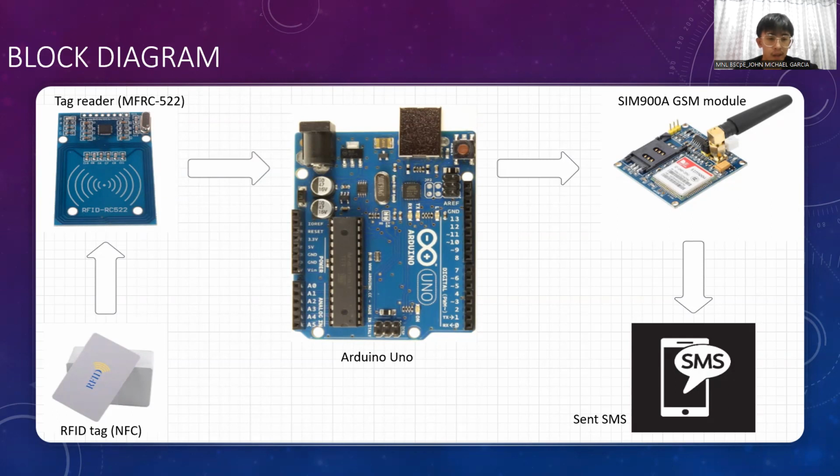And since we have arrays as an example of a database, if the student number is 20, then the 20th data will be called, where it will be the name of the student, its course or section. The number of its guardian will be pasted to the designation number of the SMS receiver. So after the SMS was created using arrays, then the Arduino Uno will send instructions to the SIM900A GSM module to send the SMS. Then the SMS will be received by the guardian of the student.